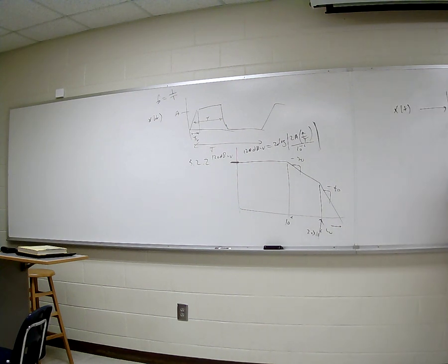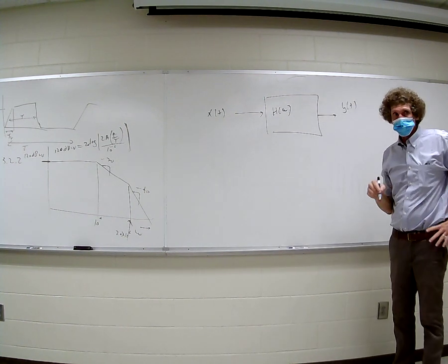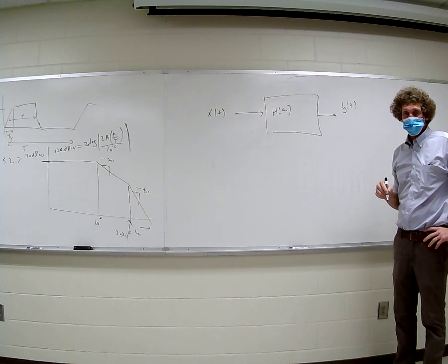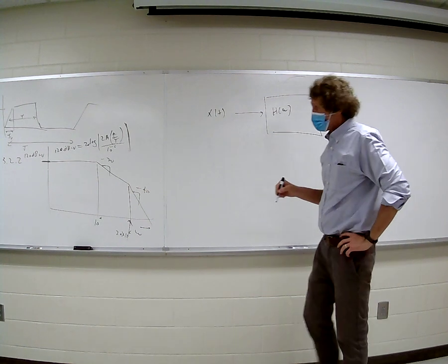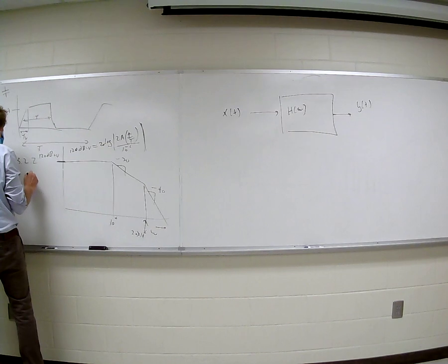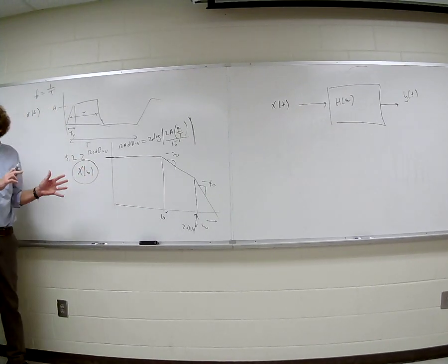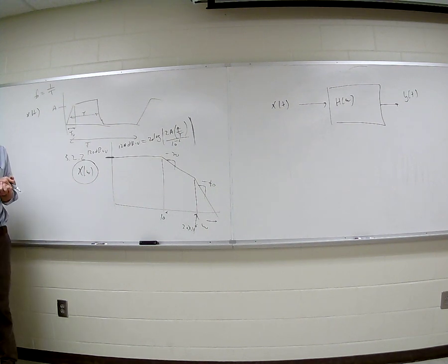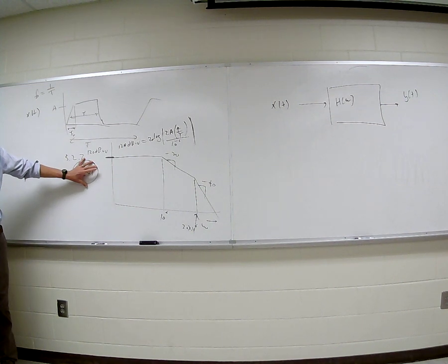And what they actually want is information about the output. Now, what are they asking for? The magnitude of the output of the system shown. So they want the entire output. Yes. Okay. The magnitude. Now, this is the frequency, this is the input, so call this a plot of x of omega. It's actually not quite x of omega, it's 20 times the log of the magnitude of the coefficients, for a phasor coefficient, the 2 times magnitude of c of n. All right, don't worry about that, but this represents the input waveform.